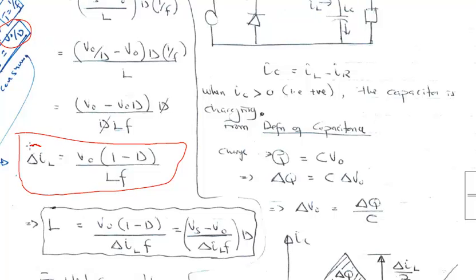If the change in inductor current is known or is fixed or you want to keep it to a certain level, then it means you can design some of the other parameters, mainly the inductor, or what should be the frequency which needs to be used, assuming the inductor is fixed, assuming our output voltage is fixed. We want that output voltage across our load. What should be that inductor which we need to use to be able to maintain the change in IL, or what is the frequency which we need to operate this buck converter with, assuming that the inductor is fixed or is known.